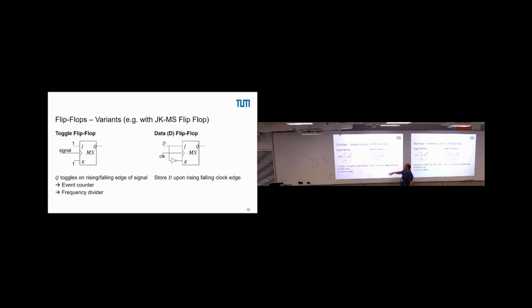So this is how we can simply transform what we had on this hand-drawn thing to implement a standard D flip-flop as you have in each computer a hundred times, a million times. It can be implemented like this. As I said, usually today you implement this with a multiplexer structure, but I don't want to go into different MOS implementation techniques. Okay, so far okay? Any questions to that? No? Good.